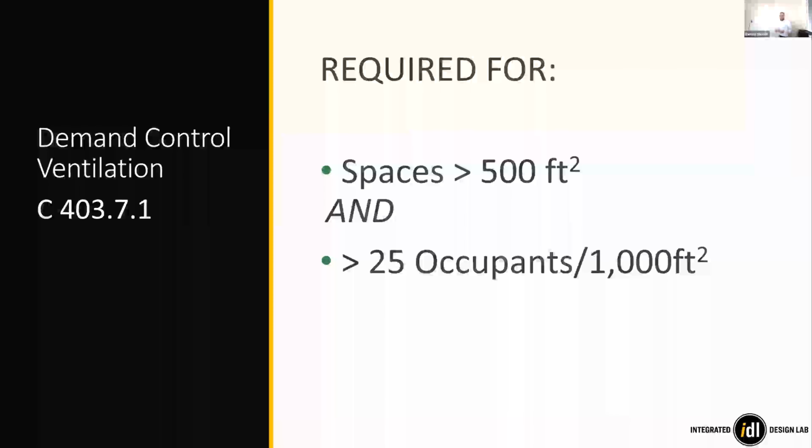So that's economizers. In terms of demand control ventilation, this is mandatory even if you do use the performance method. So doing an energy model doesn't get you completely free of the rest of the energy code. There are certain requirements that are still mandatory, and this is one of them. So this is just managing the ventilation so that we're not bringing in tons of cold or hot air when there's nobody in the building to breathe it or notice it.